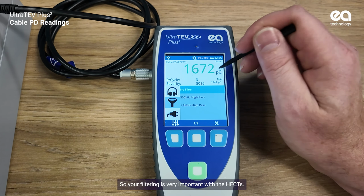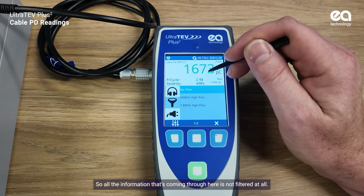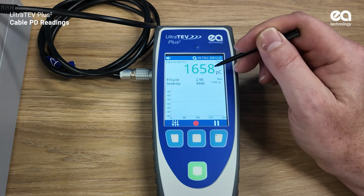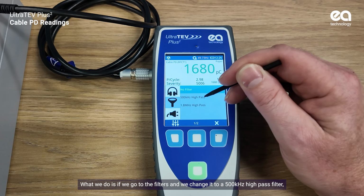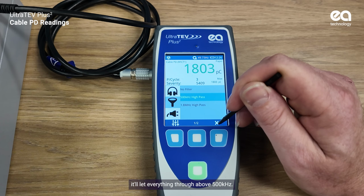Next one is your filtering. So your filtering is very important with the HFCTs. Default mode is there is no filter. So all the information that's coming through here is not filtered at all. What you see is what you get. It's capturing everything that it can. What we do is if we go to the filters and we change it to a 500 kilohertz high pass filter, it'll let everything through above 500 kilohertz.